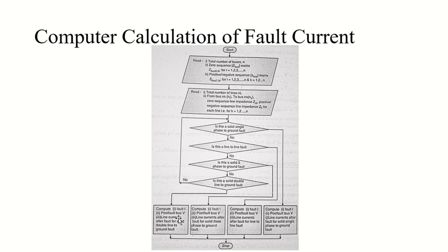The initial fault current is used to determine the required momentary duty of my breaker, and the current and the voltage a short while later are used to calculate the required interrupting capacity of my breaker as well. So it is very important to find these currents and voltages, because it helps us in so many ways. It also helps us find the short circuit capacity of my circuit breaker.